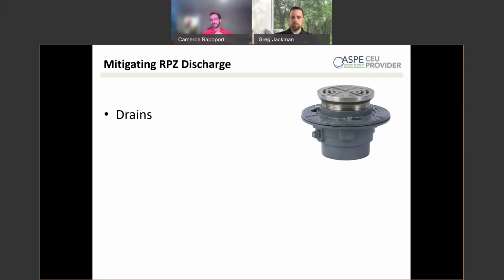So we, just like every other backflow preventer manufacturer, publish our worst case scenario relief valve discharge rates. You'll want to take a look at those to get an idea for drain sizing. If you have more questions about this, we have another CEU webinar specifically on RPZs. I would encourage you to check it out.